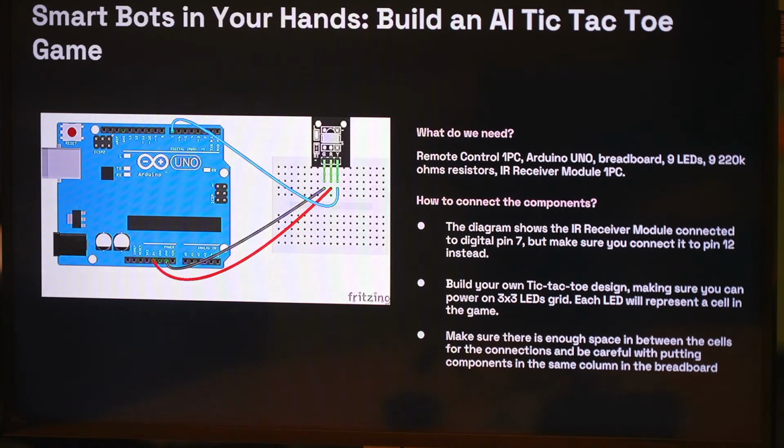I can put the red wires in 0, right? No. Yeah, 220 here. But do it from 2 because that's where the code maps to. 2? Okay. Yeah, from 2 to 10. So 2 is going to be mapping to cell 1, 3 cell 2, 4, and so on and so forth. Resistor from the negative prong to the ground? Exactly. Okay, perfect. Got it. So it's a shortcut. You don't need a wire for the negative part.